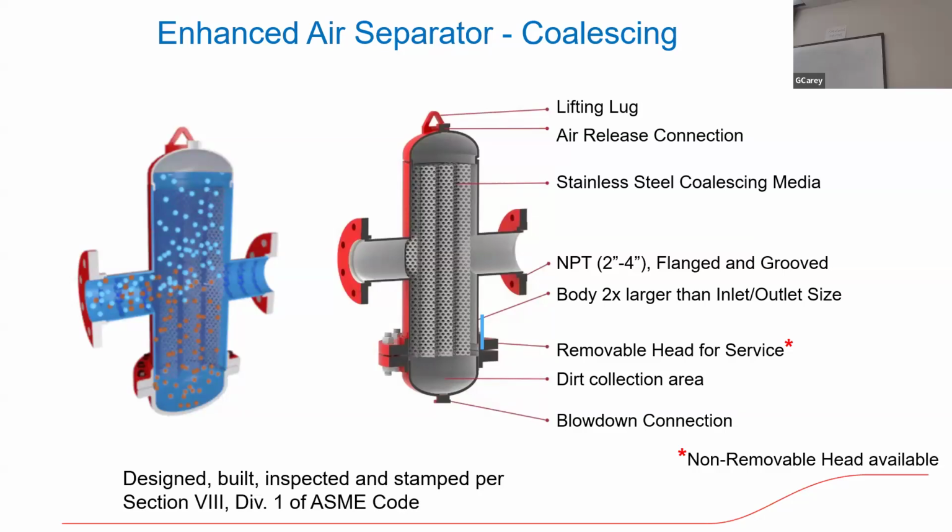Same thing, it has a high capacity vent on the discharge on the top of it. And again, it's located down in that boiler room if it's a hot water heating system, or on the return side for a chilled water system. It has a blowdown connection because we can almost use it for a little bit of dirt separating as well, connecting it to perhaps an older system that might have some dirt particles coming back. As the flow is coming back, all of a sudden it hits this wide spot and that velocity slows down, allowing some of that dirt to collect. So they'll have a blowdown valve connection on the bottom there.